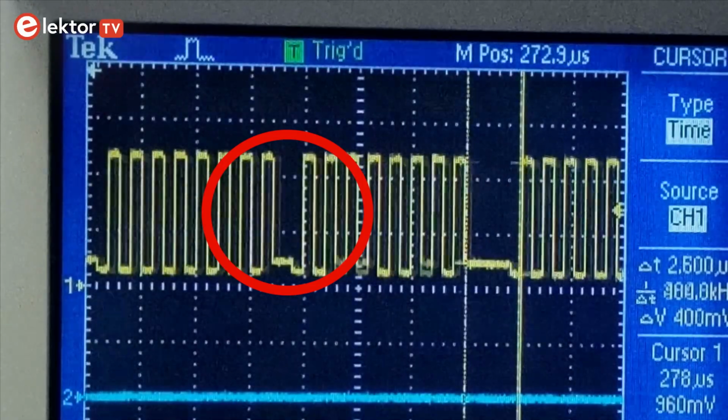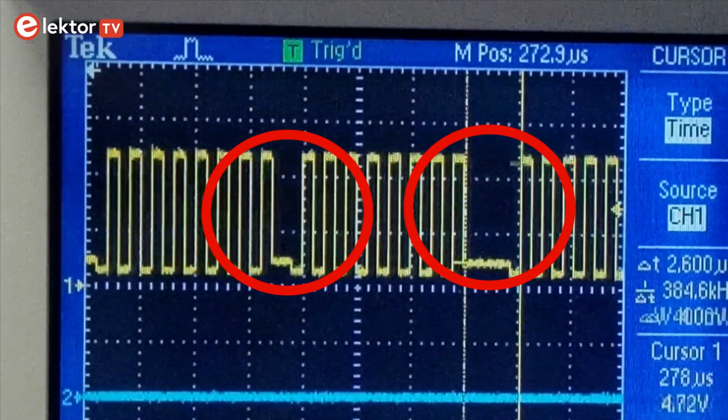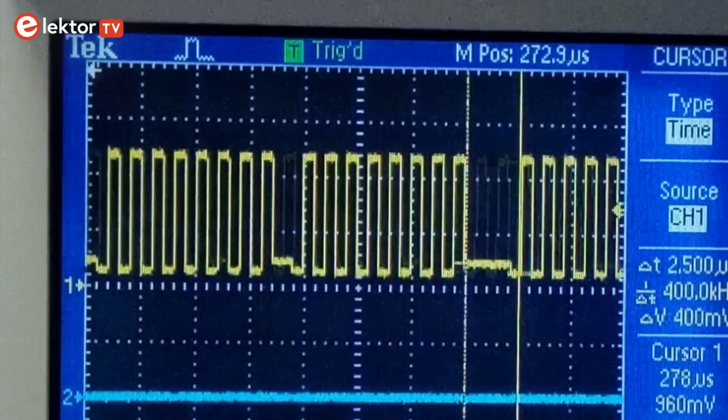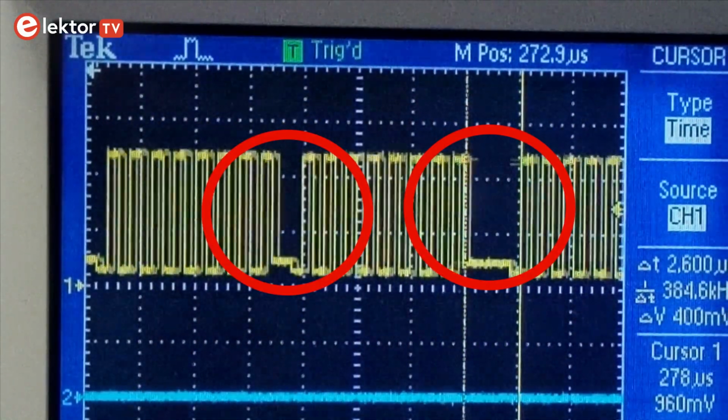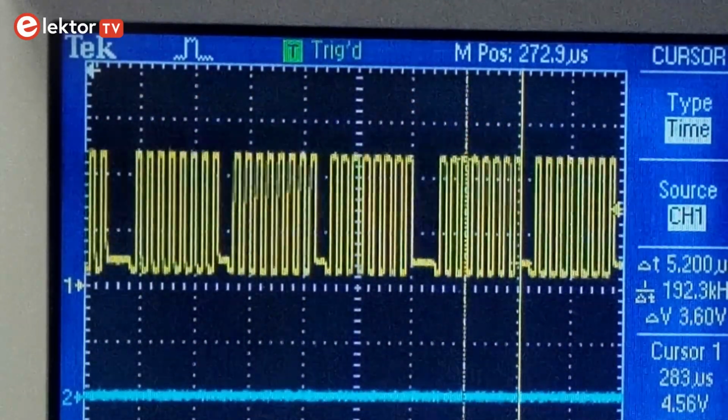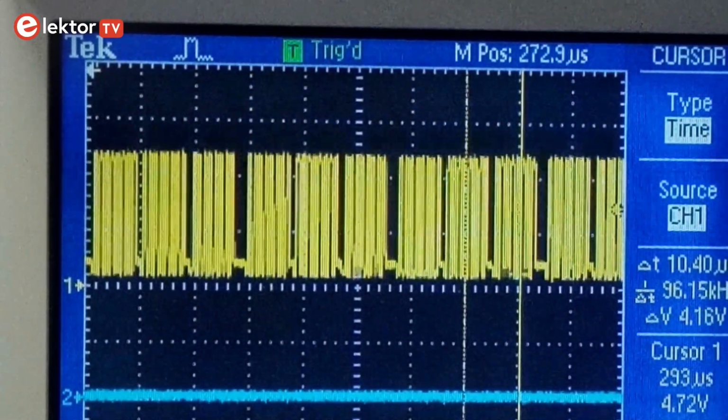I found that the idle time between data bytes is an important parameter. SPI produces a MOSI signal with the bytes separated by a delay needed to load a new data byte. When this delay became too long, my WS2812 marked strips began working erratically, whereas the unmarked strips kept on running. Officially, the data latch time is at least 50 microseconds, but maybe some devices accept a much shorter delay? The SPI data reload delay can become too long due to other processes running in parallel, like timers that interrupt the SPI transfer. It is therefore highly recommended to disable interrupts when data is transmitted to the LEDs.